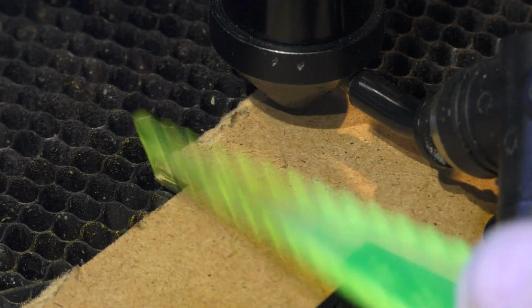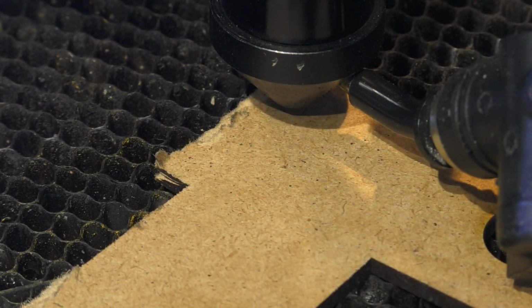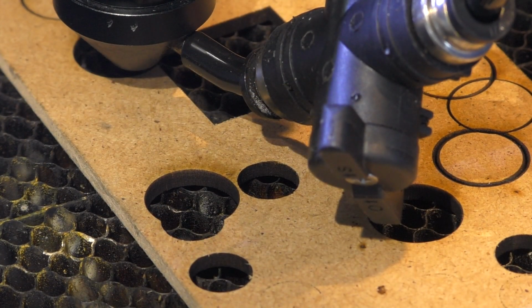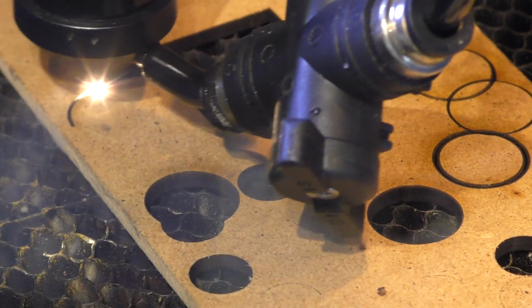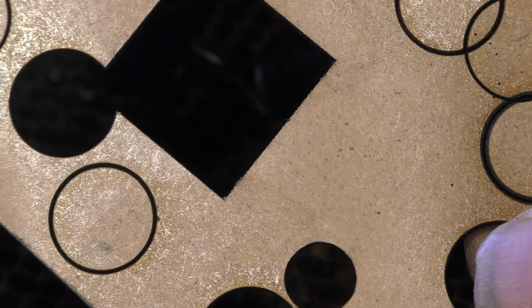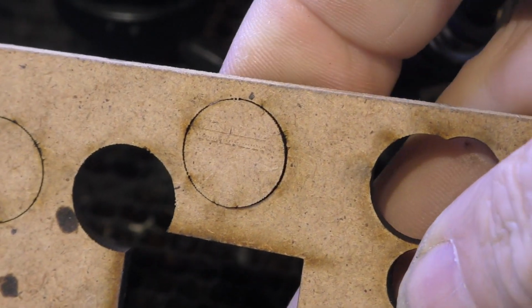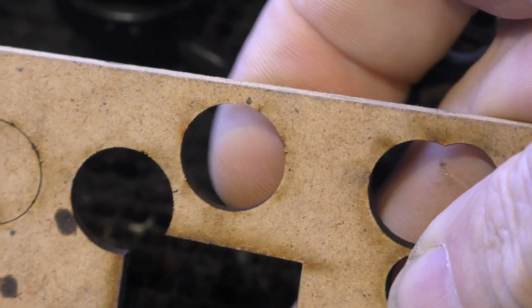Okay, now I've changed to some 3mm HDF. We've set the gap to 4mm, which is 14.5, the nominal best focal distance we've found. We run that at 25mm a second. That's quite a nice thin line, and look over the back. Well, yeah, it's just about coming out. Look, oh yeah, we can pop it out very gently.